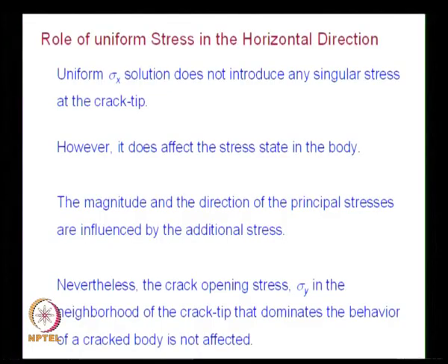So, in the initial stages of fracture mechanics development, if you are confining your attention only to the close vicinity of the crack tip, use of the term sigma x really does not affect, because the crack opening stress sigma y in the neighborhood of the crack tip that dominates the behavior of a cracked body is not affected. From that point of view, it is justifiable, but you have to keep in mind that after looking at the generalized Westergaard equation, none of these solutions are accurate. You have to go for a multi-parameter solution for any problem of practical interest.